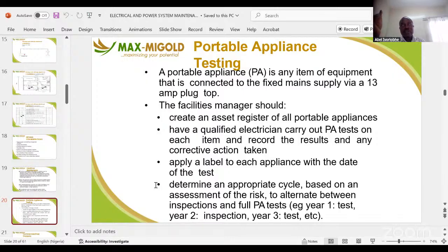Diesel test is key. If you don't test your diesel when it's supplied, you can just be accepting diesel that has been compromised. And it will keep damaging your generator. It will damage your equipment. Your AC will not work well. Every now and then the generator is jerking, and it will affect the performance of all your equipment in the building. Your lights are going off, they are burning because your power is not clean. If you do all these things and keep records, at least you will save cost. Are we together?